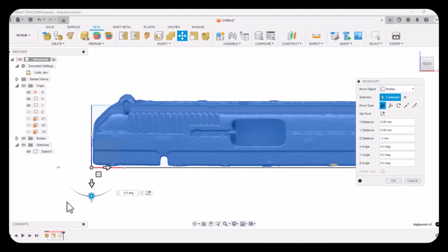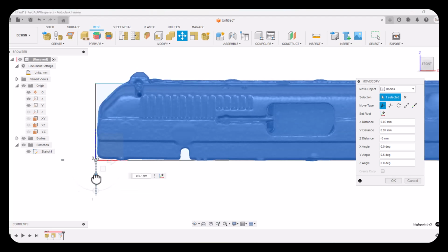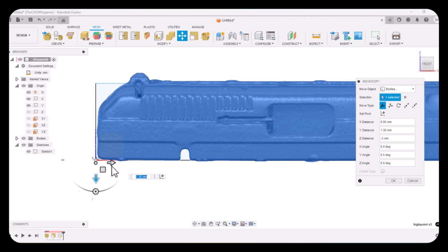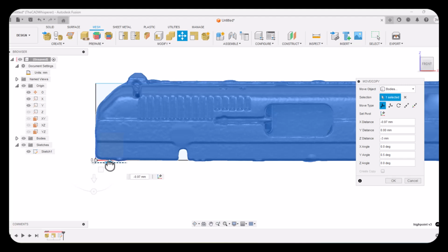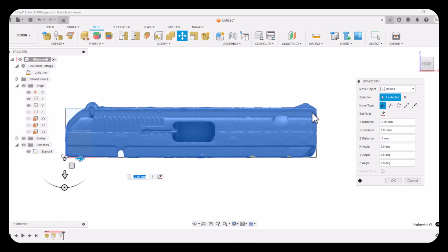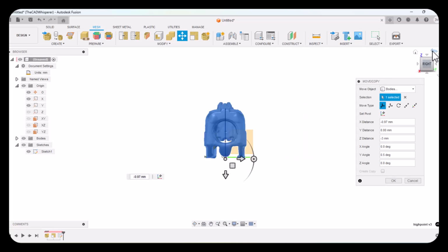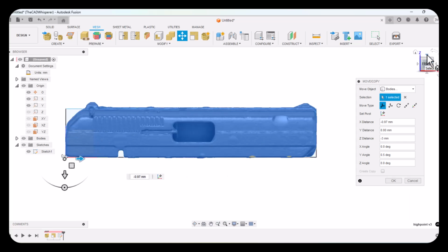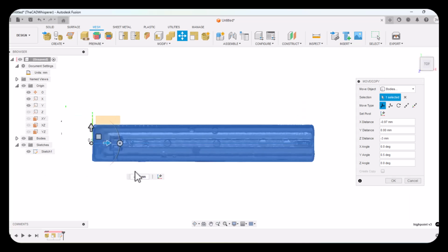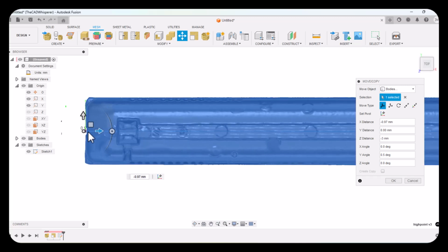And so I've changed this coordinate system, so I'm going to reset this again on the origin, then select done, and I'll move down some, I'll move over some, and I'll check it from the right side view. So that looks okay from there, and I'll check it from the top view. Now I might want the origin to be right here for the fixed jaw.